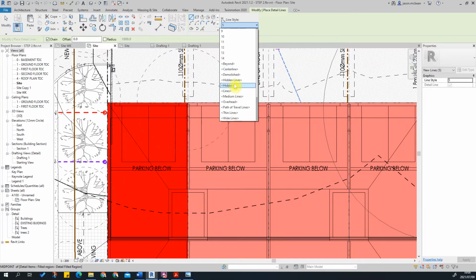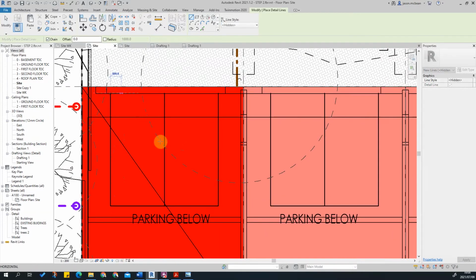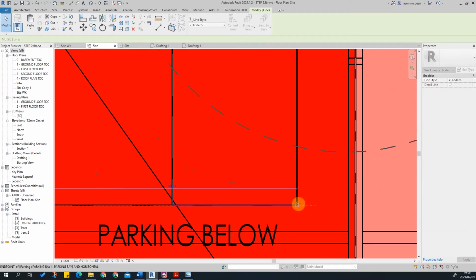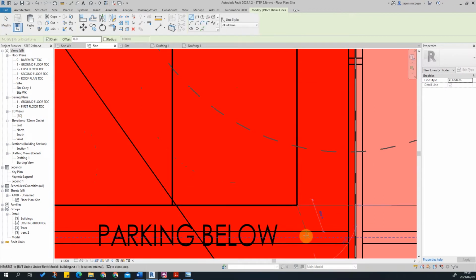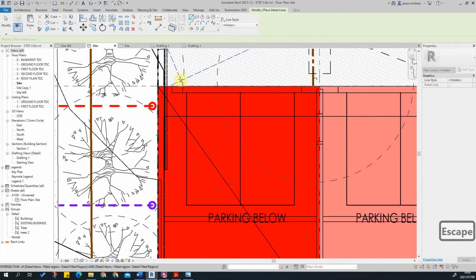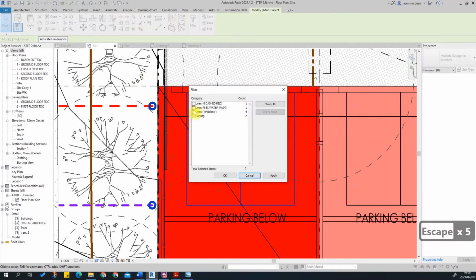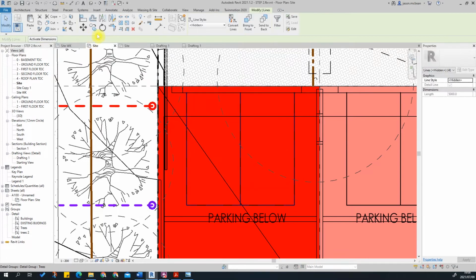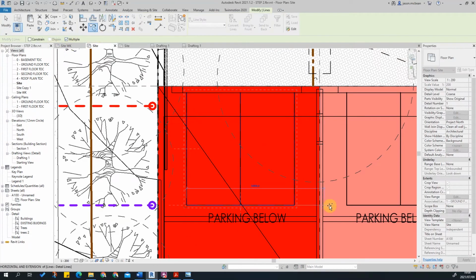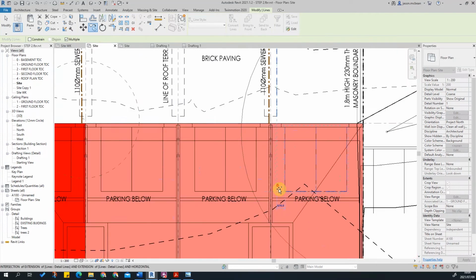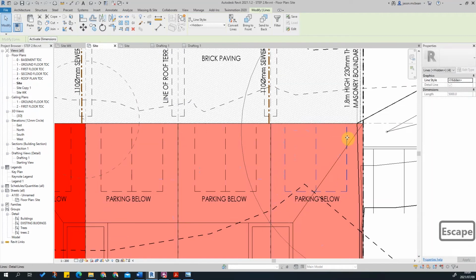So you can simply go and use the hidden, and you just need to do this once, and I'll copy this line work. So once I've completed that, let me just do that a bit more. Let's take this to here. Right click, create similar. Pull this down from here to here. Okay, now I can simply just say select. Use the filter command, check none, and I want the lines hidden. And I'm going to simply say copy, make sure multiple selected, copy, copy, copy, copy. Okay, hidden. Okay, that's good.